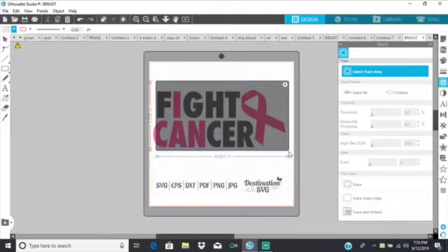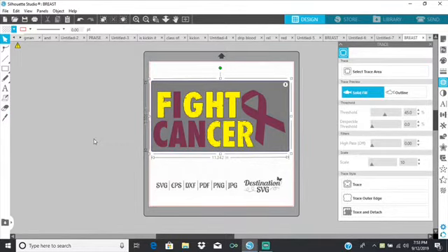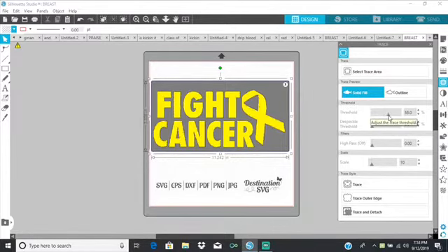If you have a pretty detailed image and certain things that you don't want in the image, you can always clean it up. Here's a little eraser tool over here, just in case you need to do that. But I'm not going to need to clean it up. This is a pretty nice image. So this one is not going to be hard to do at all. As you can see, it only highlighted some of it in yellow. You want the entire picture to be in yellow. So to do that, you're going to go over here to where it says threshold, and you're going to play with it until you can get the entire picture to turn yellow.